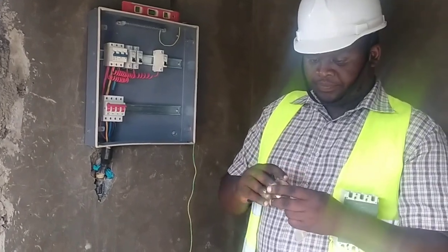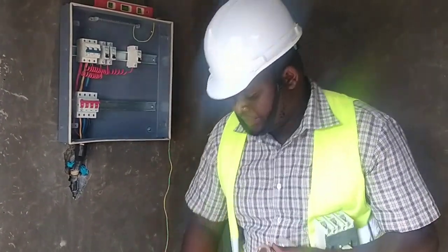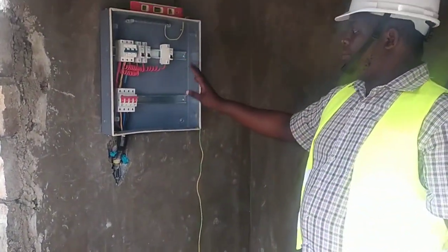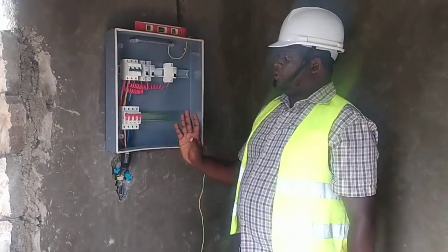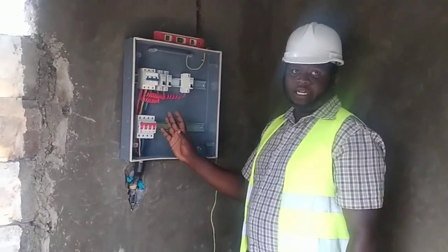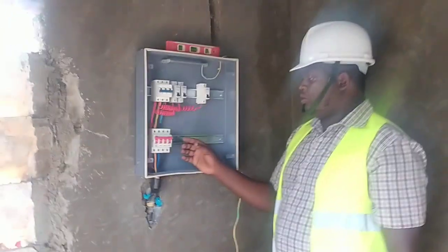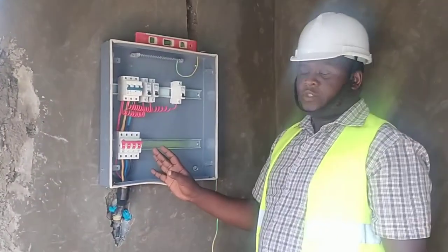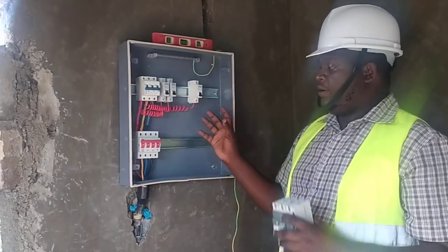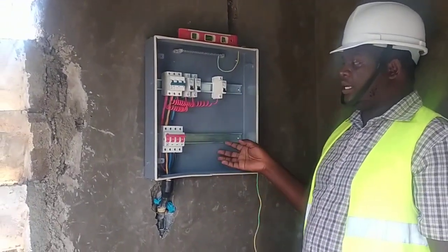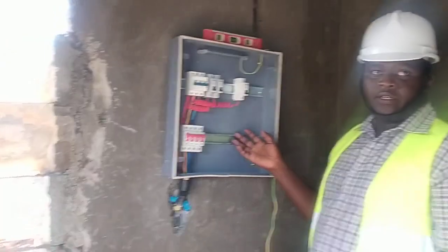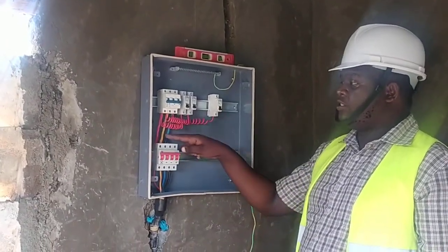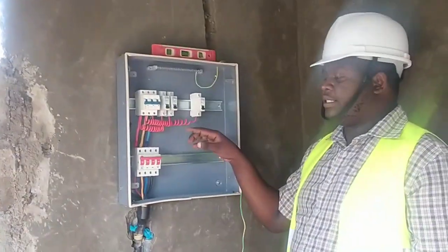So that is basically it. When you are mounting your cables, you need to decide the sequence depending on the country you are in or the process you want. If you do RYB, you should stick to RYB. In our system we have automatic phase balance circuits, but there are instances where you will need to do the phase balancing as a technician.